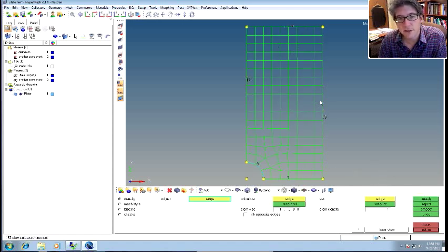And you can see here it gives me a mesh. That's not a bad mesh. If I like it, I can hit return. If I don't like it, I can hit reject. Let's say I wanted to add some more nodes here. You can actually do that. You can use this element density, and I can individually pick an edge. So if I pick the edge, it set it to 1, because that's what I had the value set to.